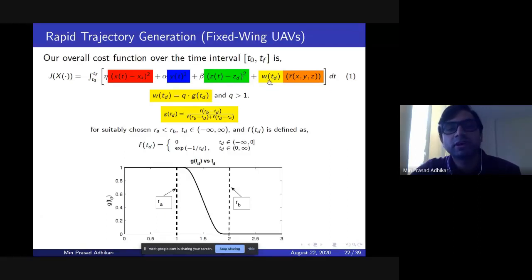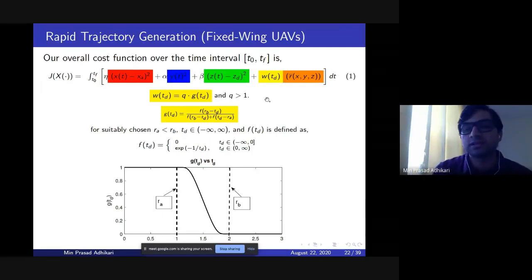So these are the penalty parameters, like how much priority do we give to obstacles? It depends on how far we are from the obstacles, right? That will be an ideal condition. Suppose you have 20 obstacles, and if all 20 obstacles are affecting your trajectory generation all the time, that is not something you want to account for. Those obstacles are really far away. So you want to take only those obstacles that are nearby, and you want to avoid them.